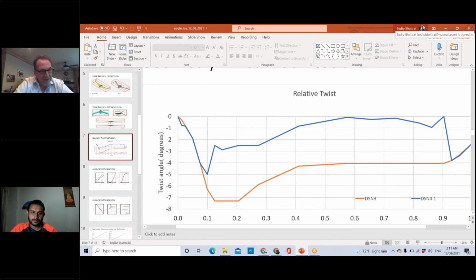and that's okay. And then just do some approaches to stall. To exercise it, I would do some approaches to stall just straight in. I'm sure you're doing that already. And then I would do some turning stalls where as it stalls, it develops side slip. And then that'll really get it going and see if it has a spin propensity. And then do a before and after where you do some straight in stalls and do some turning stalls. And maybe always use like a 30-degree bank angle and then just slowly stall, something like that. And take a look at if adding washout helps get rid of that spin propensity.